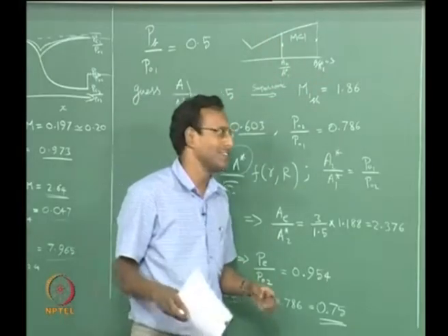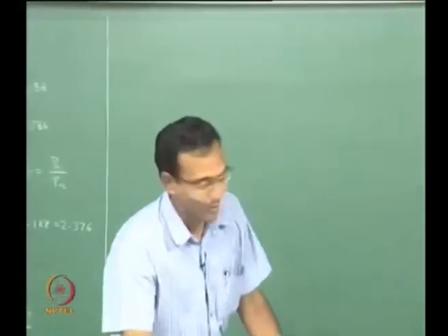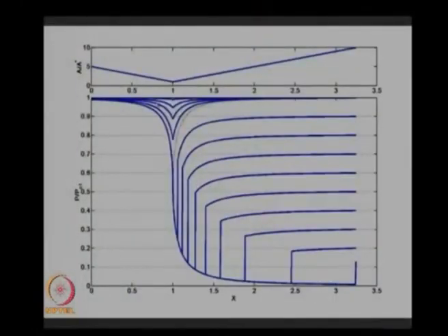If you do not like the explanation, let us go to the screen. All I have to do is just remember that as the shock goes downstream, the pressure at the exit drops. This is the only thing you need to remember. If you remember this, then things are easy for you automatically. I did not want to choose this exact nozzle because you can just use this plot and give me answers. I picked a nozzle with exit area as A by A star of 3. This happens to be 10. I just picked some other case. So all we know is if I want to decrease the exit pressure, my shock has to go more downstream. Now we will go back here.